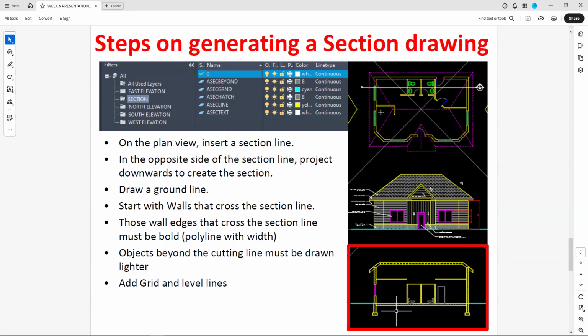Okay, there's the roof line, and notice that the section line is cutting the roof at this level. That is why if you project the intersection of this diagonal line to the section line, that will be the intersection of the slope here, and you're actually cutting away the roof, showing some of the rafters. Okay, and then you're showing the ceiling and then what is inside.